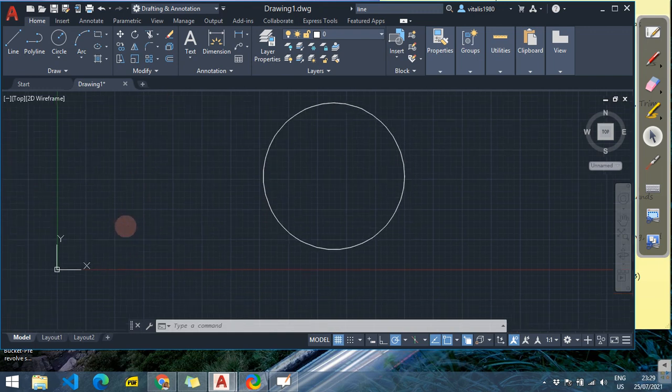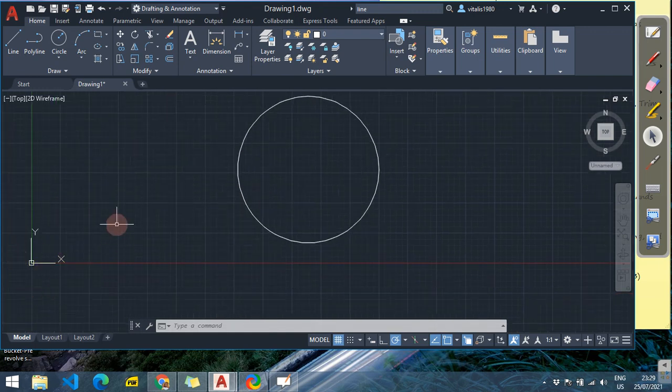But now the next thing we need to talk about is our WCS and UCS. Right now what you're seeing is the UCS, the User Coordinate System. We also have a WCS here. By default, the AutoCAD UCS is aligned to the WCS. The WCS is invisible, it is a fixed point on the graph, and the UCS is always aligned with it.